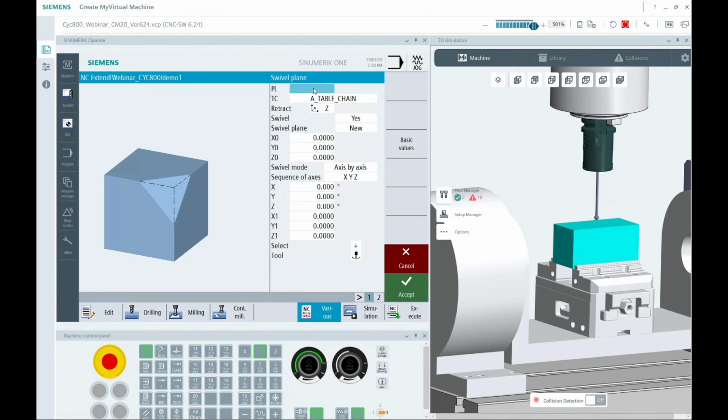Now within it, you can define what plane you're working from. Generally, it's going to be G17. I don't need to because I have the G17 in my safety line. But if not, I can certainly put it. It's not going to hurt me either way. Now, usually what you're going to see on your machines is only one kinematic type. In this case, for this demo machine, I have 2, and we're going to explore why that is a little later when I show you the back-end setup functionality. But for now, it doesn't matter which we choose. I'll just use the classic.